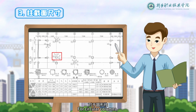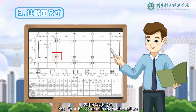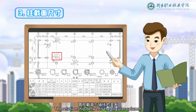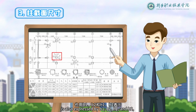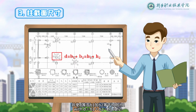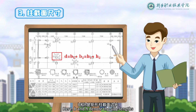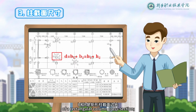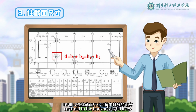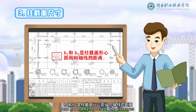For circular columns, the b multiplied by h column in the table shall be replaced by the diameter prefixed with d. The relationship between the circular column cross-section and the grid lines is also expressed by b1, b2, h1, and h2, with d equals b1 plus b2 equals h1 plus h2. Here, b and h denote the side lengths of a rectangular column cross-section. b1 and b2 represent the distances from the column centroid to the horizontal grid lines, and h1 and h2 represent the distances from the centroid to the vertical grid lines.